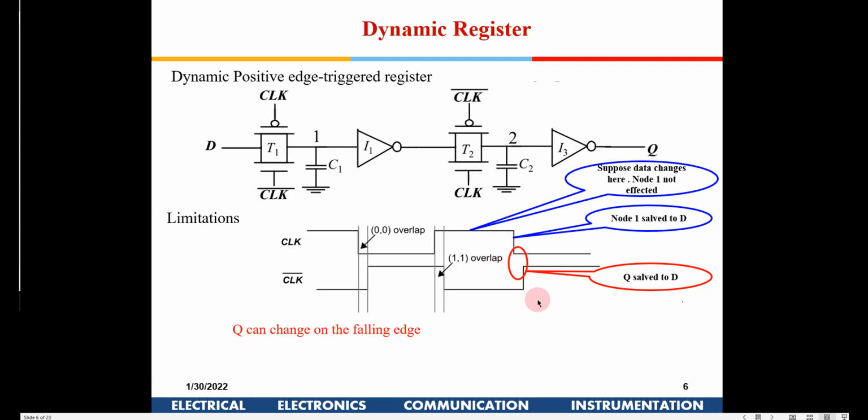For this second issue, there is a solution available. If you see here, this is the time from here to here. If you keep the total intrinsic delay of one pass transistor plus one inverter plus one more pass transistor greater than the jitter time, or in other words, if you keep the jitter lower than one pass transistor, one inverter, and one more pass transistor delay, then in the negative sample, it will not get sampled out here. Is this aspect clear to all of you?